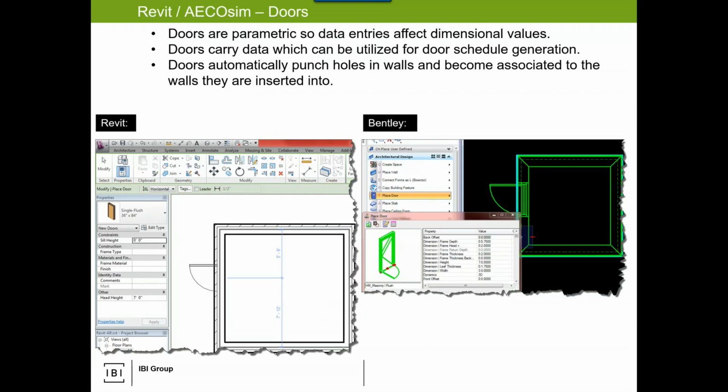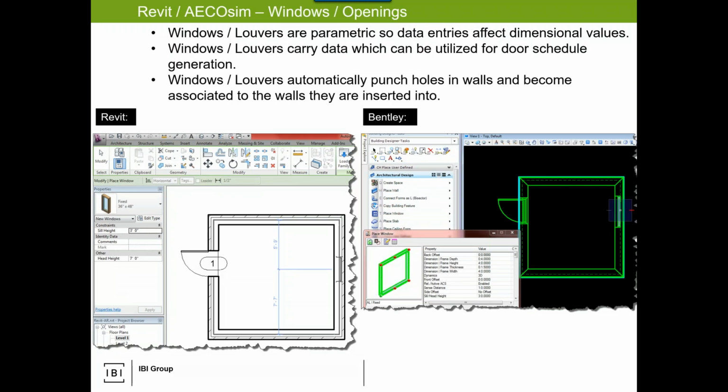Place doors. The beauty about BIM is components like this are parametric, therefore meaning they will cut components they're supposed to cut. They will interact, frame, connect, etc. And they will contain both geometric plus non-geometric data to facilitate scheduling, for example. For an architect, the door schedule is this beast that we must do every single time. This saves so much time and money. Same with windows, cut through, interact with the components, parametrically driven, connected, so they move with the components they're in.